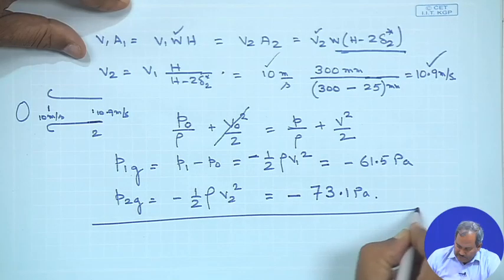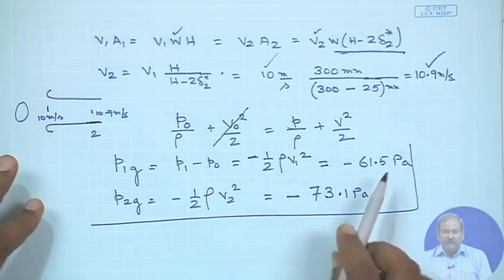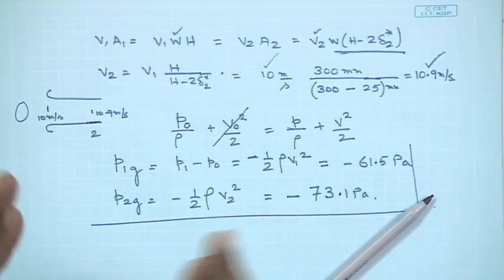So, the precondition for the use of Bernoulli's equation is that we must transform this viscous flow to an inviscid flow problem, and I can change viscous flow to inviscid flow only when we use the concept of displacement thickness. The moment we use the concept of displacement thickness, the area available for flow has now reduced by an amount equal to twice delta star from the top and from the bottom. And since the flow area has reduced, the velocity has to increase.